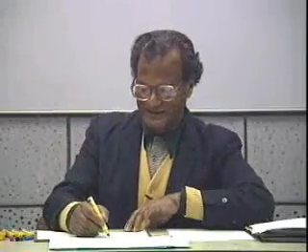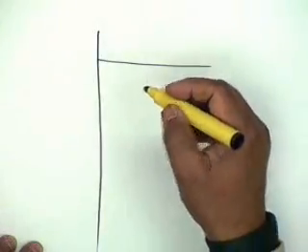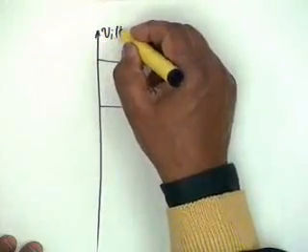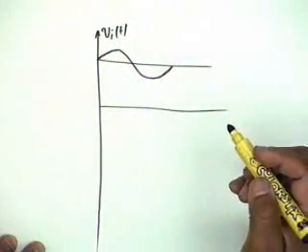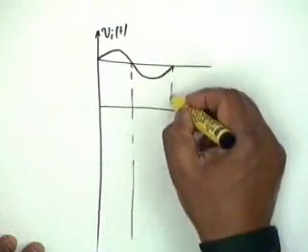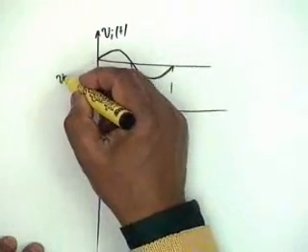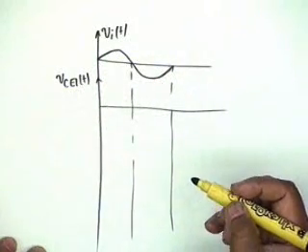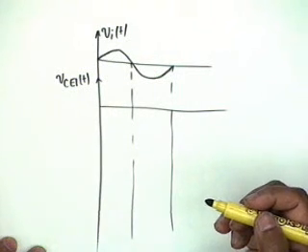But before that, let us look at the power distribution in the class A amplifier. Okay, it is instructive to draw these diagrams. Let us say my VI(t) is of this form. I am drawing only one cycle, all right, only one cycle. Draw these vertical lines. Suppose this is VI(t), then VCE1(t) would be VCC minus VO(t), okay.